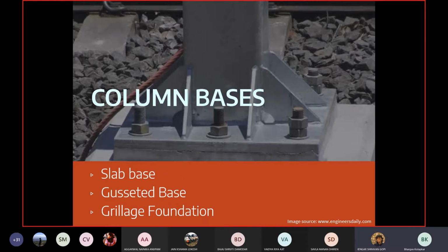Directly, as in, sorry, I didn't understand the definition of directly here. Like just putting it on it and casting the floor, or why we need a gusset plate in it? So why do we need a column base? Why do we need this base plate? Why can't we place this column directly on the concrete footing? We need something to holster it or bolt it to the ground, because steel requires a lot of complex joinery in terms of bolting or welding. Okay.